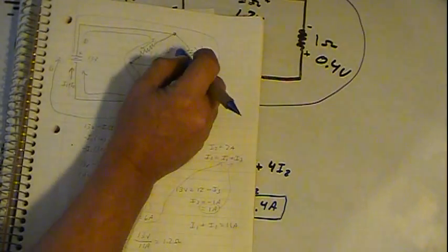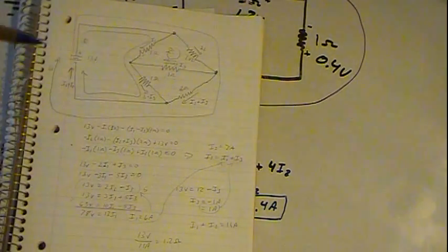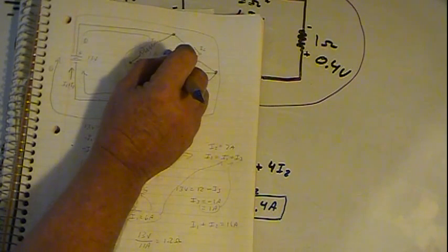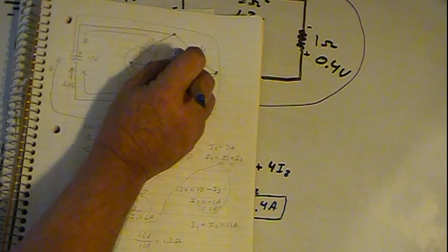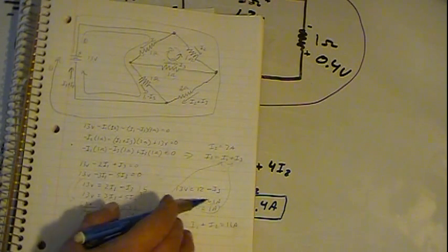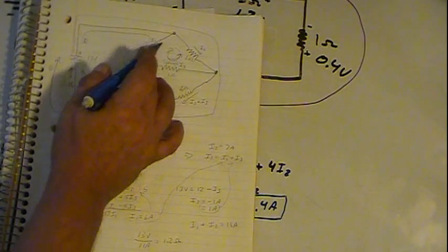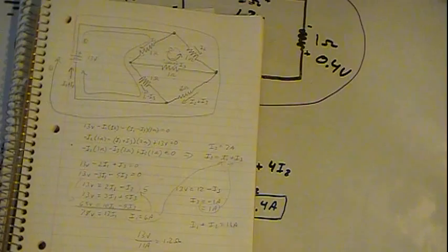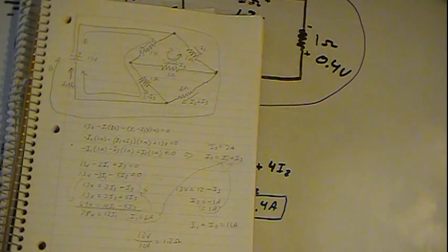And actually it's this loop right here, loop 3, that needs to be reversed, not this current flow here. That current flow was actually correct. But anyway, that's what this negative meant: this loop, because that's where this actually came from, was going the wrong direction. I had it this way, it needs to go this way, and then it will come out positive. You can't have negative currents.